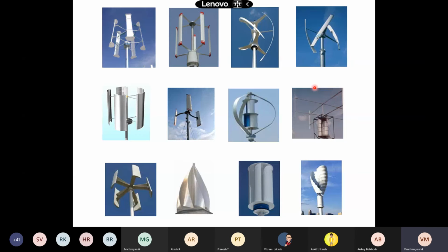The power we can usually obtain at the end of the third stage and the beginning of the fourth. That is, during the fourth stroke alone we avail the power, and for the other three strokes we need to have power. Therefore, we usually provide a structure in order to get the power for the other three strokes. That is usually called a flywheel.